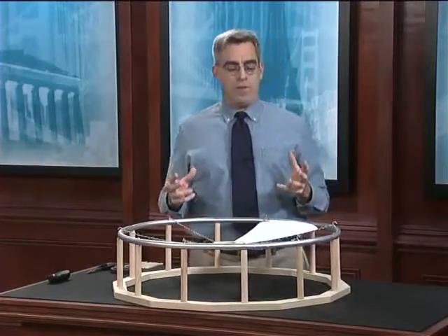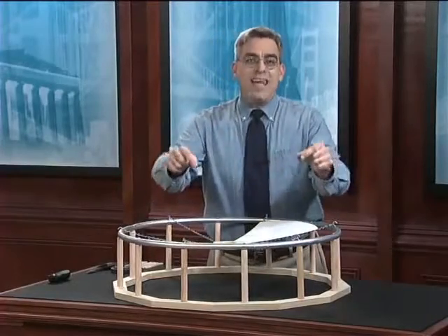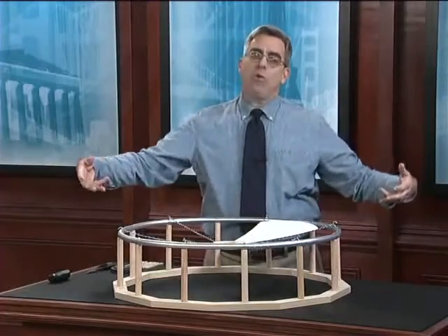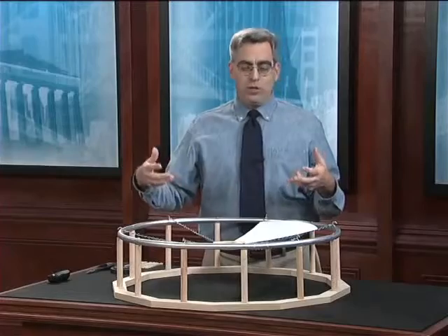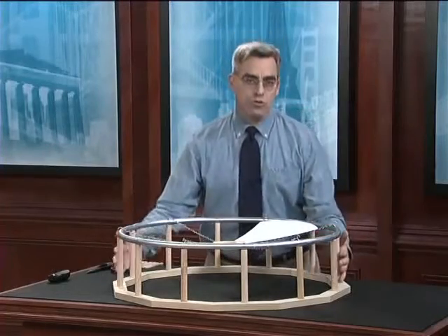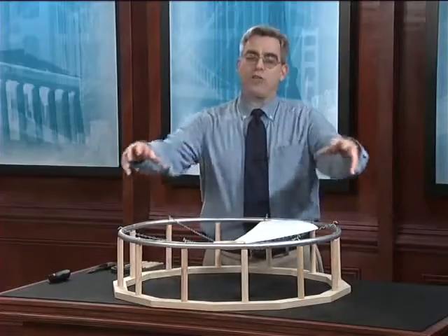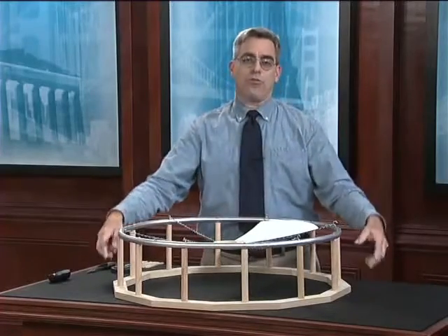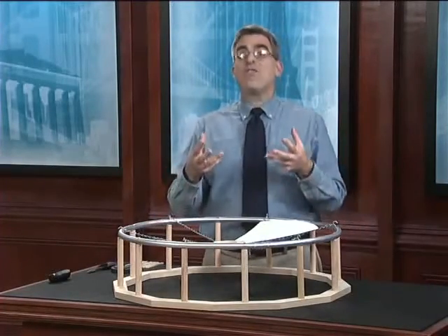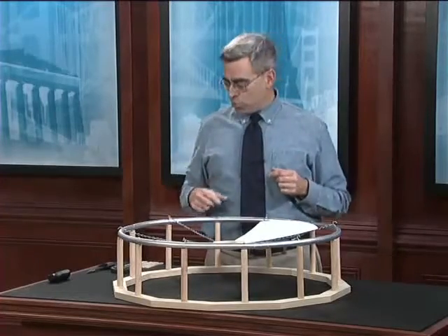It's in equilibrium. There is no net outward thrust or inward pull transmitted by the roof system to the structural system below the roof. The only load that's transmitted from this roof system down into the structural frame and down into the foundation is the weight of the roof and the weight of any load that's applied on top of it.